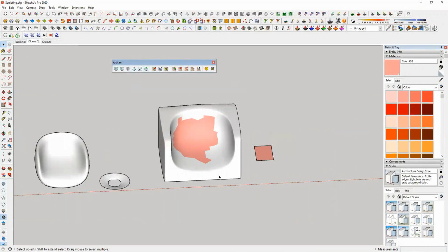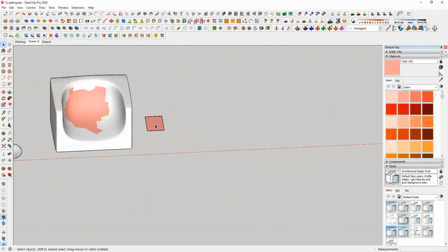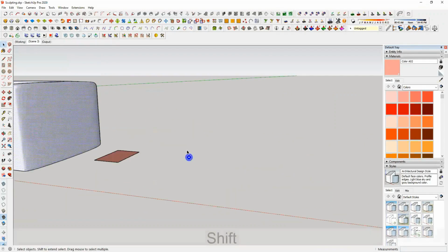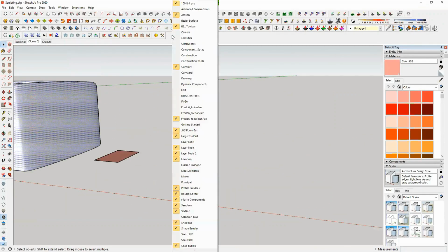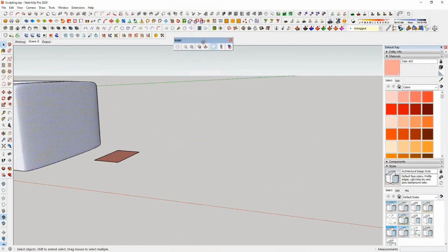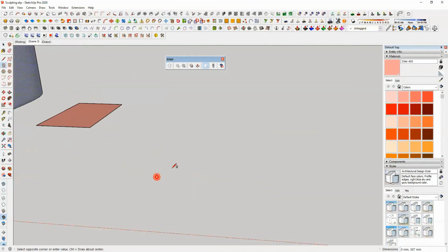So next up is using a similar tool, which is called subd. So we have the subd tool, which stands for subdivide, and that will also help us create a similar kind of effect, but we have got some more flexibility in that tool. So let's turn the subd toolbar on, keep it here floating. So let's start with a rectangle or a cuboid.